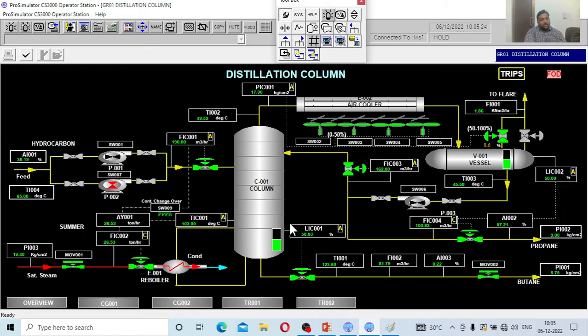We have seen the flow controller here, the level control here, and the split range controller here. What else? Another level control. You can see the product which we withdraw from the reflux drum depends on the level. You can see the level; it is now maintained at 50% reflux drum level. The moment more vapors come in, the level is going to rise. Accordingly, the level control system is connected to a flow controller. This is called cascade operation. The primary controller sends a signal to the secondary controller, and this secondary controller decides the opening of this particular valve.